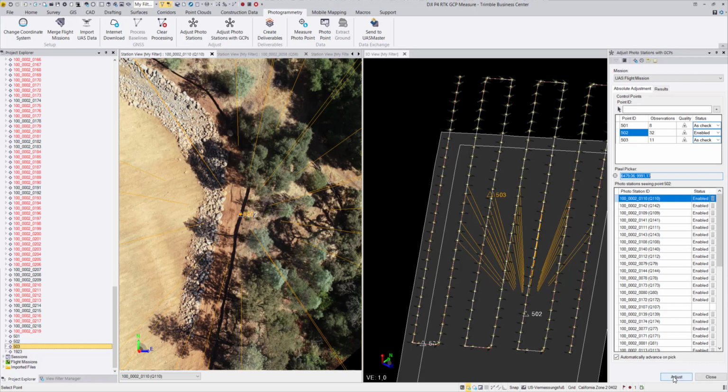So when we hit the adjustment button again, because now we have a different constellation, I recommend you to take a look also at the video about block configuration, because now we have, additionally to our GNSS, which has a high precision, also a ground control point with a high weight, and therefore we will again calibrate the focal length.